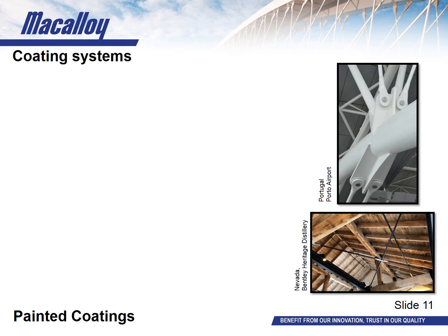Painted coating. We're now going to give an example of a 3-coat paint system consisting of a primer, intermediate and top coat. Each coating is specified depending on the system requirement for protection and/or aesthetics. The coating or film thickness, generally specified in microns, is key for safeguarding the base material. The paint specification should be provided to Macalloy to guarantee the right system for the application. And to keep the end client happy, of course.